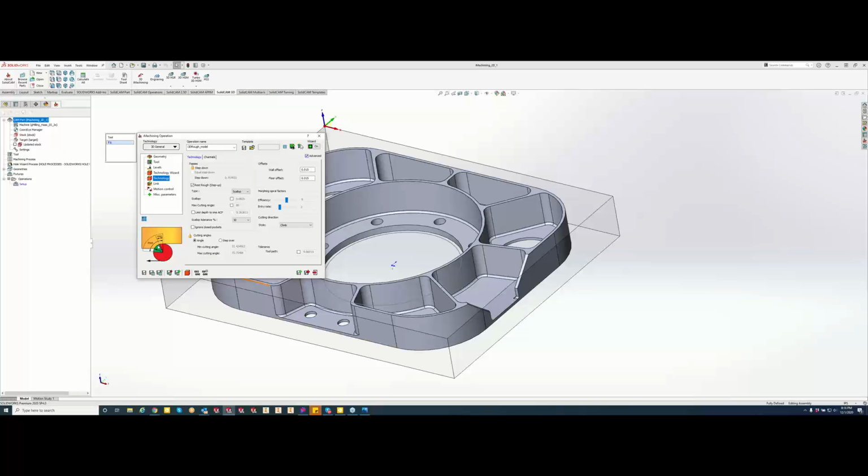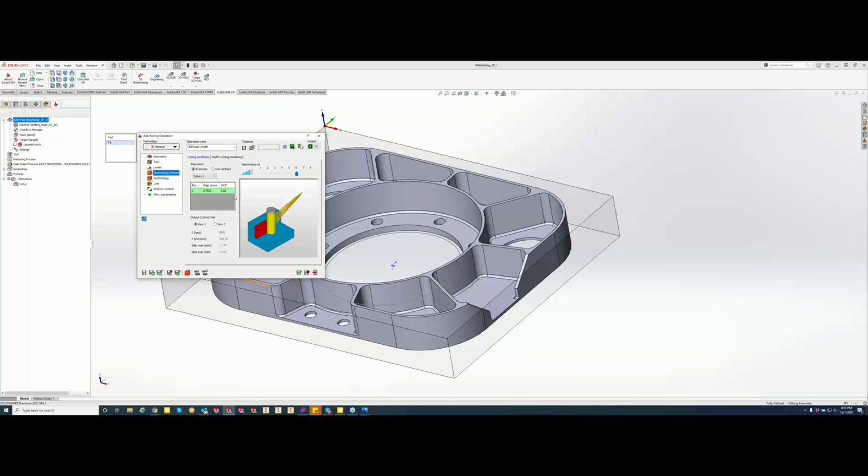Just go. So right here is our flute angle of engagement. Basically the ACP is the actual contact point of that flute engaging into the material. That ACP value will change based off of the number of flutes that you have versus the diameter, helix angle, and all that. So sometimes you will have green in here with an ACP of maybe 1.0, whereas when we were yellow here, we were at an ACP of, I think it was 2.4, something like that, but it was still coming in yellow.